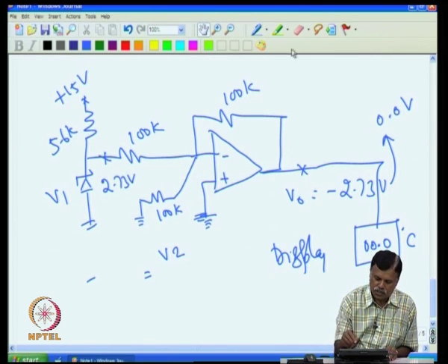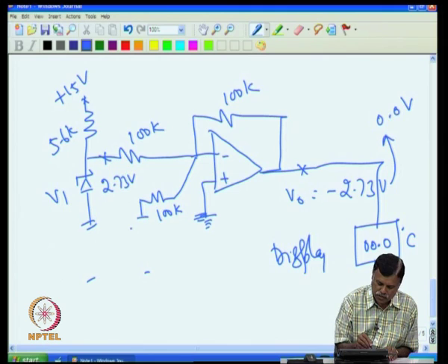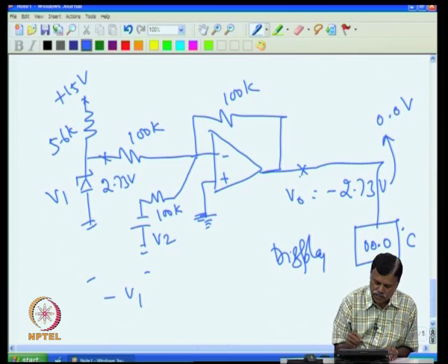So, already those are familiar. Maybe you need not struggle so much. You can say that the two voltages here, this is V2 and the other one is V1. The net output is V1 and the gain is 1. So, V1 is anyway inverted, so output will be minus V1, and V2 again the gain is 1 and that is again inverted, so I will have plus V2.